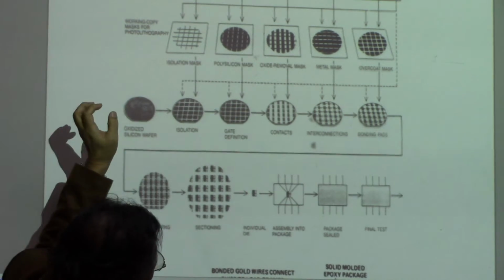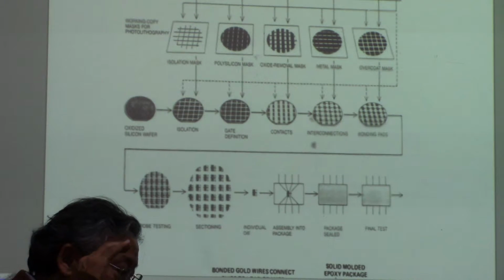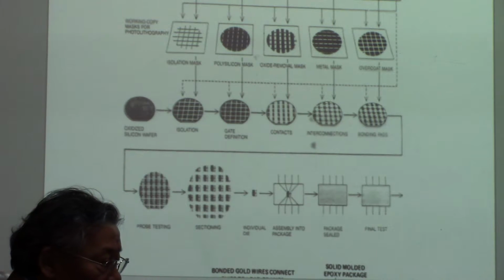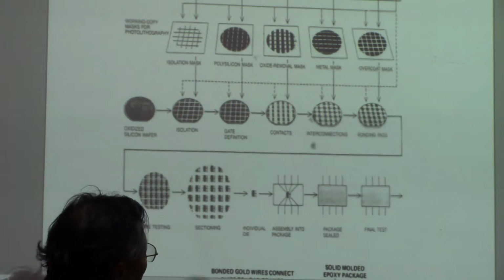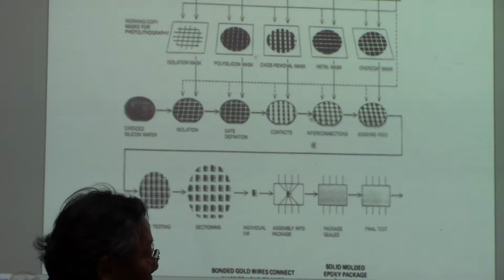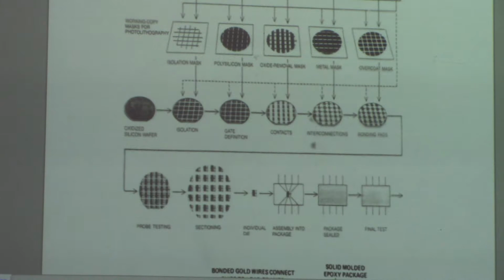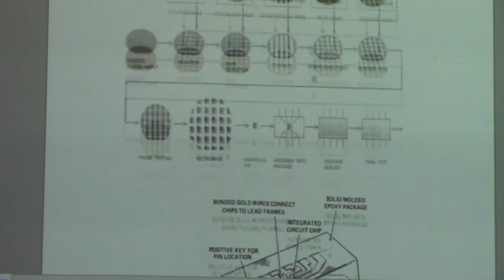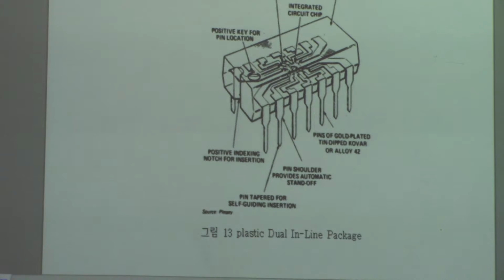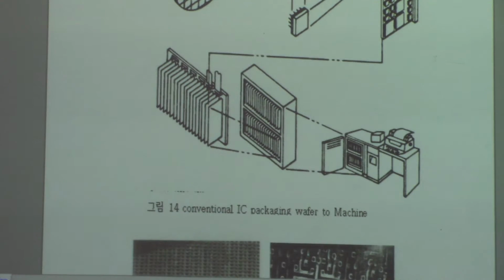different masks. We had a lot of lithography, and making a thin film on top of the silicon wafer and etching. Repetition of those things, we build up the transistors, okay? And the function of the transistor is the same as the vacuum tube, okay? And we can make the transistor very micron-sized transistors through here. And then that is encapsulated in plastic packaging. So all these figures are related to that.